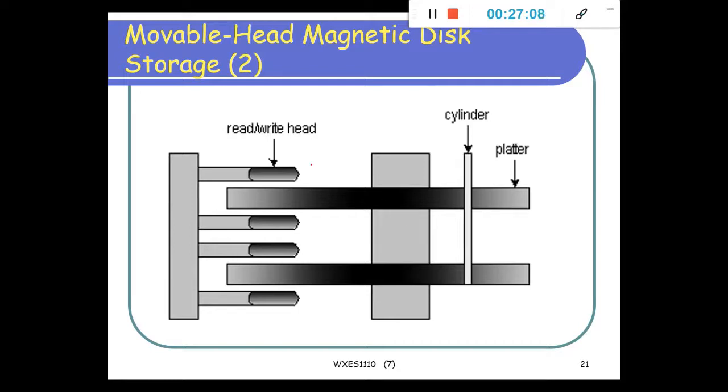Okay, this one read-write head will move on the different tracks or different sectors. The arm moves the read-write head between each pair of surfaces, the surface above and below it, the top and the bottom. The arm moves all heads in unison, meaning in one direction. If one head is on track 36, then all heads are on track 36.